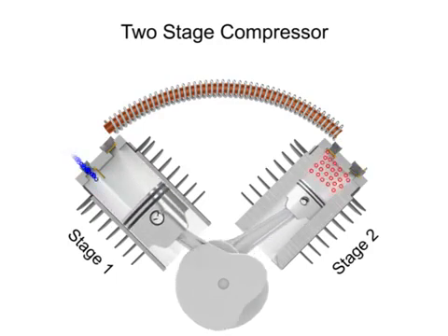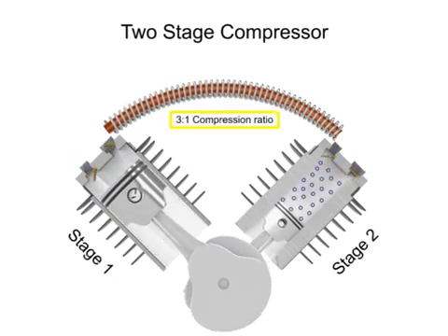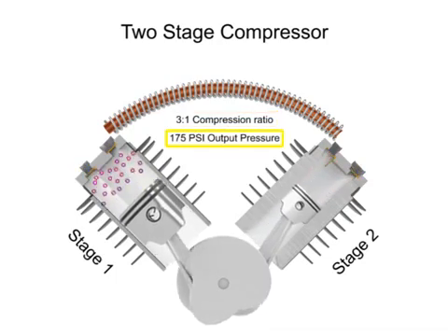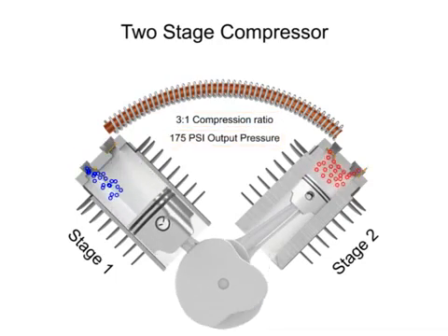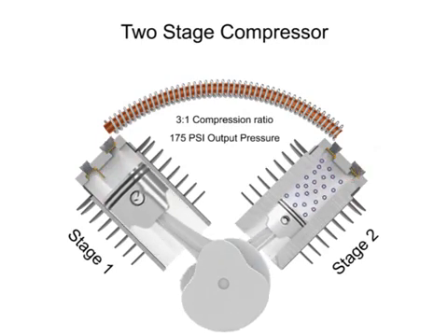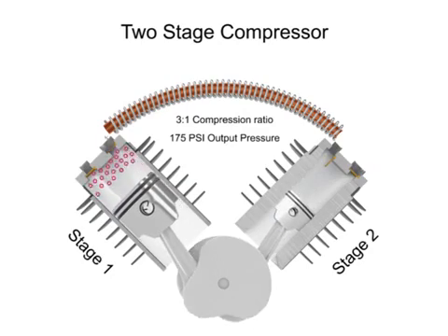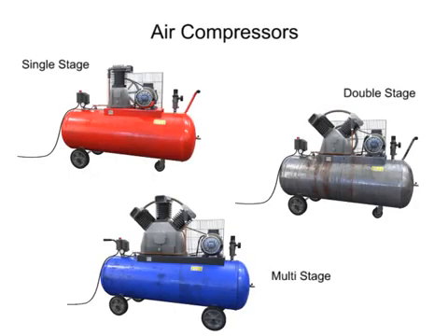Two-stage compressors have a compression range of 3:1 or even less per stage, but can operate up to 175 psi. They can also deliver more air at a higher pressure than single-stage compressors of the same horsepower. If pressures of more than about 175 psi are needed, multi-stage compressors should be used. On these larger compressors, cooling may take place by circulating water instead of air. To reach a pressure of 2500 psi, as many as 6 or 7 stages may be needed, with cooling between each stage. Their versatility makes compressors one of the primary components in air production.